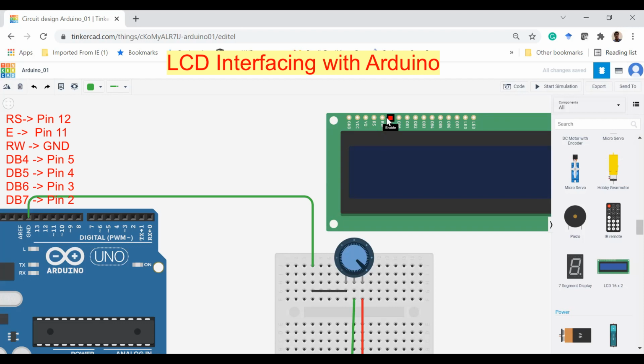Those 3 pins are basically control pins. RS stands for register select. Before sending any data, we first have to send some control signal to this register, and the register select performs different LCD operations. You can clear the content of the LCD, or set where the pixels will be shown. This is one 16x2 LCD, so we have 2 lines, and each line has a total of 16 characters. You can set the position by setting the appropriate value in the register select.